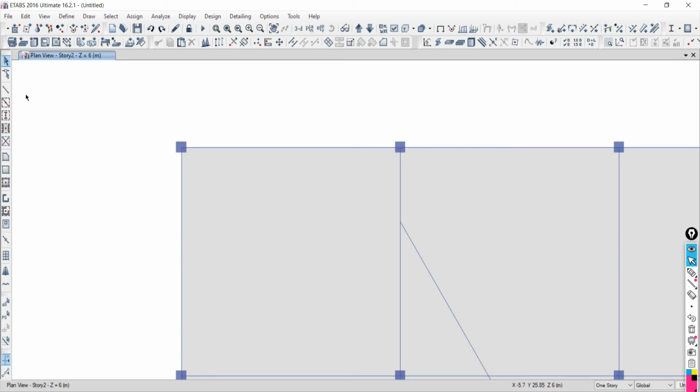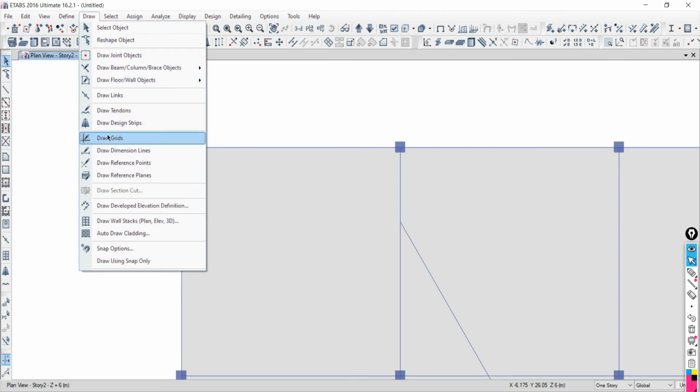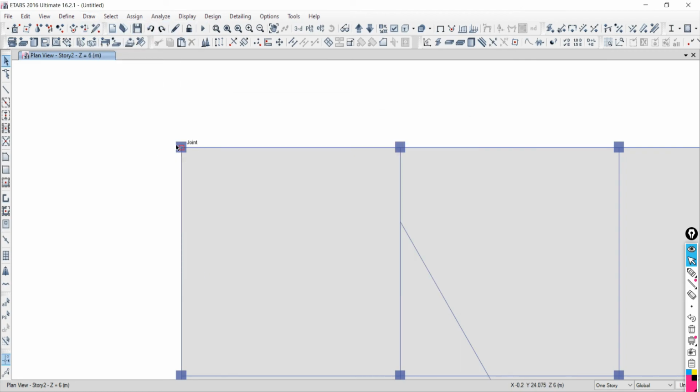Then how to turn this off? See, go to draw dimension line. First point you have to click as the start point, and at this point I would like to know. So I take your cursor, it will clear, the right sign will be there. Then 8 meter. I don't want to click over that. Just right click on your mouse. So this command's continuity will be temporarily off, but the command will be active. So go to select object to turn off the command to have the neutral action. Okay. Is that all clear? So we can even check with the help of move option, no?